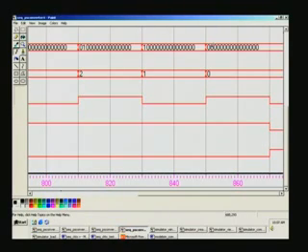So the very last must be 1 because it's a left shift. In 0 1 0 1 0 1, right? The last bit will be 1. So after 16 shifts here, data valid goes low, and end of conversion is activated here, and this completes the parallel to serial converter, and we'll go on to